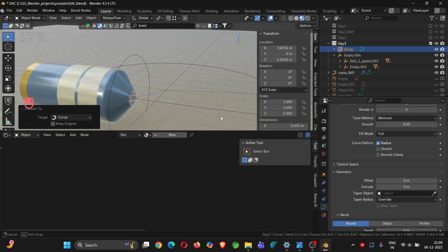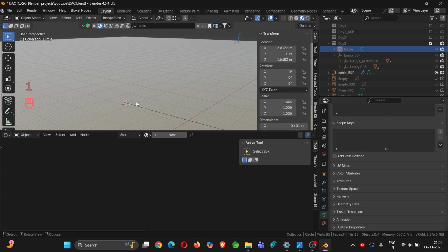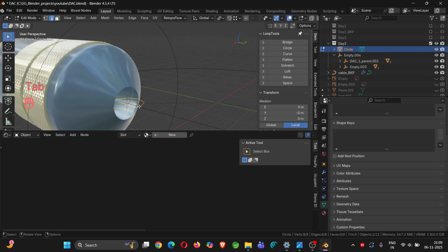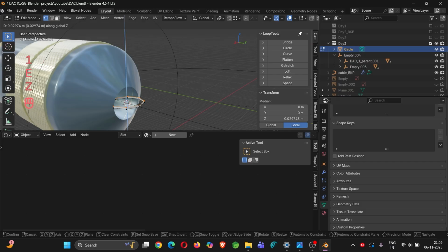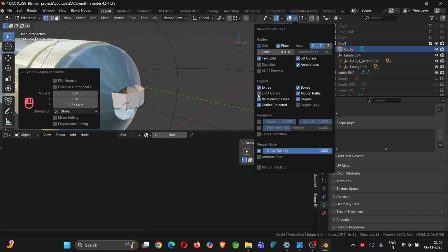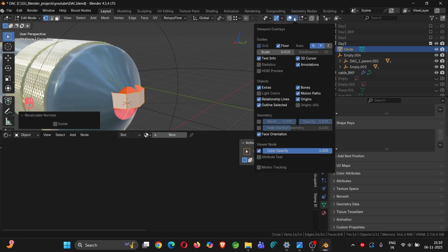Now look at the beauty. No, sorry, that is a different approach. Okay, I again hid my thing. Now I go to edit mode, and with vertex mode selected, extrude it along the z axis like this. Let's verify the face normals. It is incorrect. That also I explained in another video. If you haven't seen that, please go see. You will learn many new things from there.